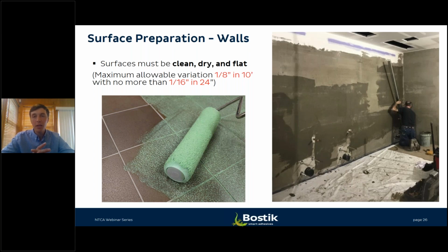You'll find that needs to be addressed on both existing applications of, say, tile over tile, which now have primers that exist in the marketplace that can allow for or facilitate the bond of a tile mortar to an existing tile surface, certain epoxy coatings, and a variety of other substrates. So these tile over tile and leveler primers allow for a great high bond strength to be developed ahead of both mortars and patches.